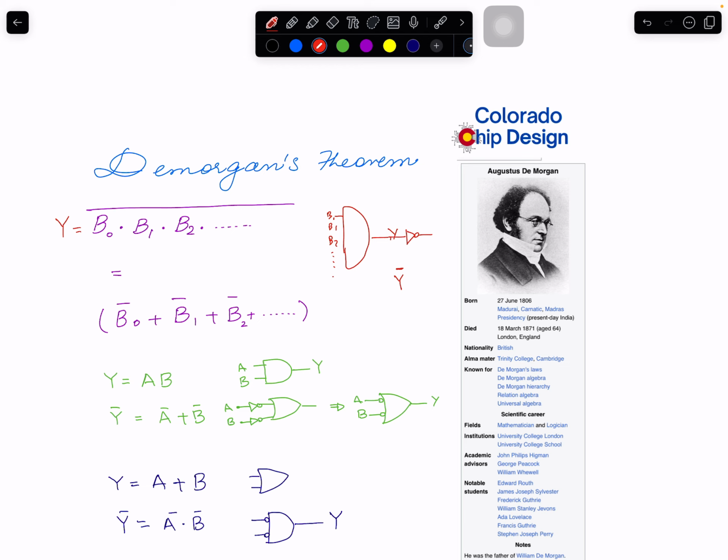But say I don't want to put an inverter, I just need some different inputs. I need an OR gate with a certain combination, and this time it will be Y dash, because this will basically be written for zeros. This is written for ones, but again the result will be similar. What happens is when you do this, you just invert each of them and you OR them. So what you will have will be B0 inverter, B1 inverter.